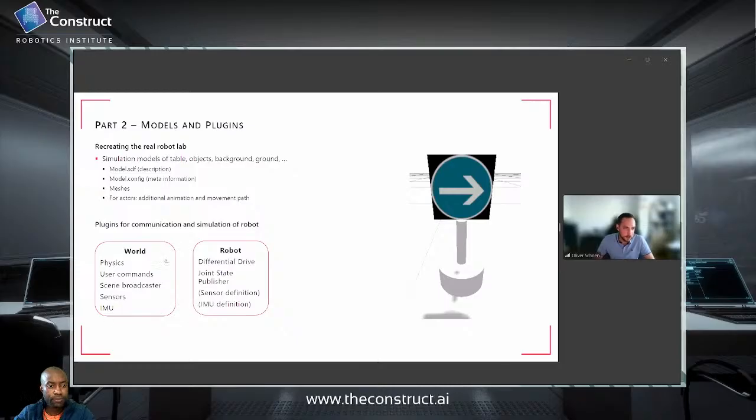So for the world, I put in here, for example, the physics plugin. Of course, we want some gravity. We want that the objects, if you are running into them, are properly reacting to it as we would expect from reality. We still also want to be able to do the user commands in the simulation. There is the scene broadcaster. We also now, the two special things, want the sensors in the world. So we want to say that in our world, we have sensors that will also be giving information to the outside. The first thing is the sensors more specifically for the laser scanners, but also then for the IMU.